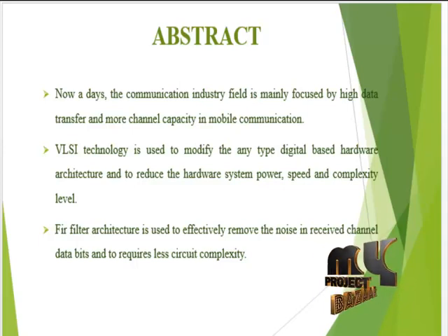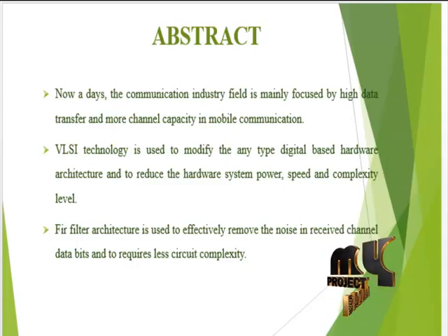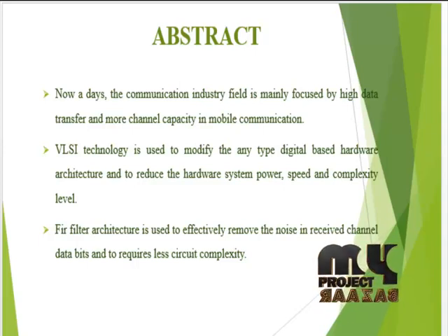Here we are using the fundamental building block for the digital signal processing process. FIR filters are important for the high speed and low power realization of DSP processes. In the FIR filter transposed direct form structure and the direct form structure, the pipelined structure reduces the critical path delay.